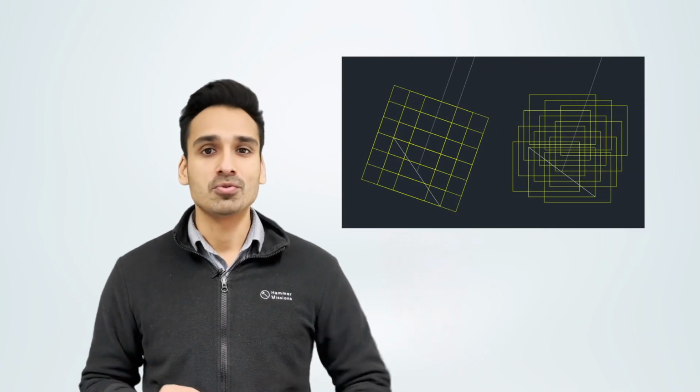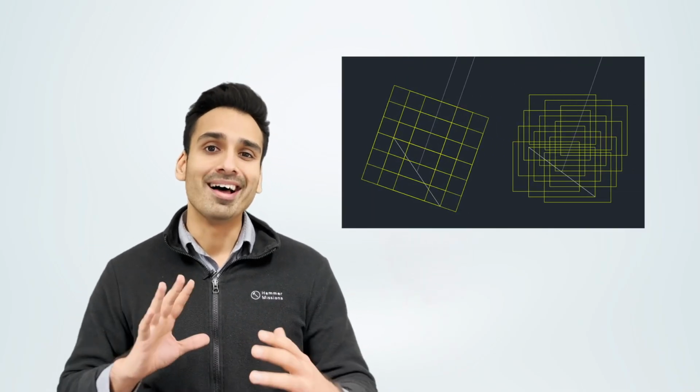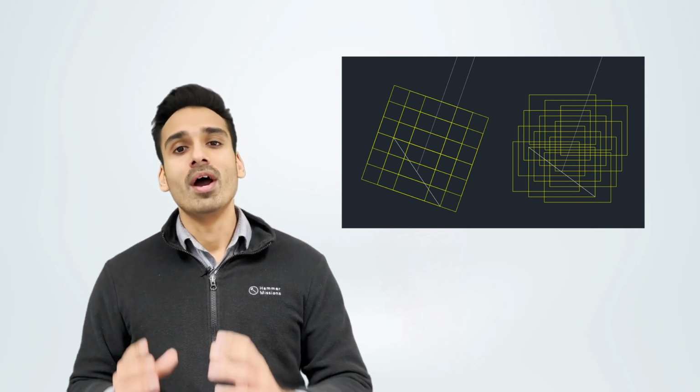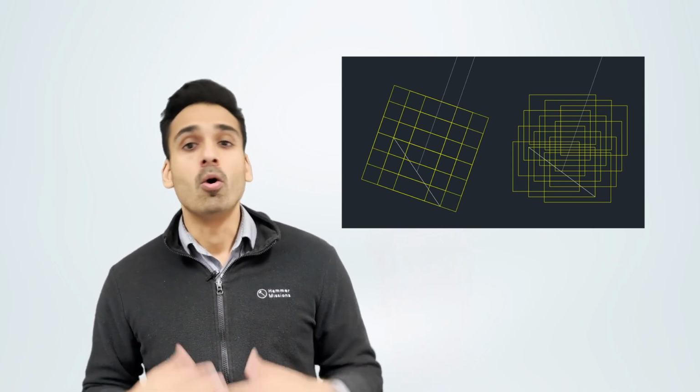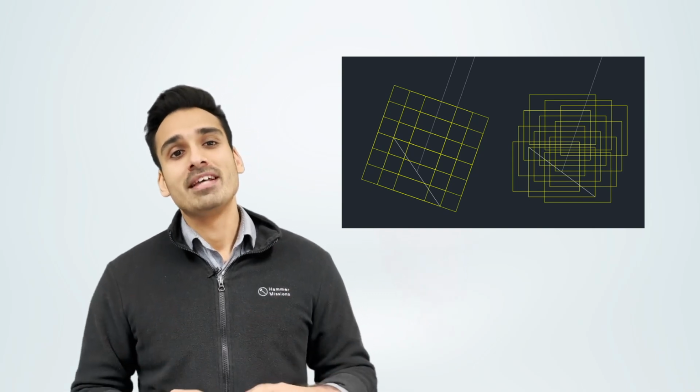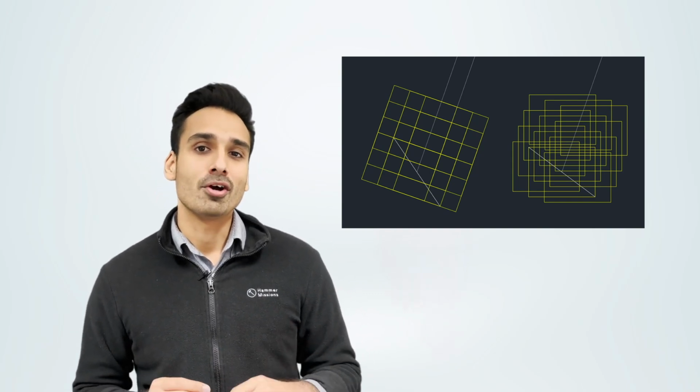Alignment or aligned images. So when you create a 2D map or a 3D model, you use the process of photogrammetry, which was what we described earlier. And one of the steps in photogrammetry is aligning of the images. And what this means is that when you take images from the drone from multiple different angles, you want to make sure that those images actually align with each other. They agree where that 3D object actually is, or where that 2D object really is. So that is basically alignment. The step is called alignment. So you want to make sure that if you take 1,000 images, all 1,000 of those align, or as high a percentage of those images align, because that creates a better quality model.